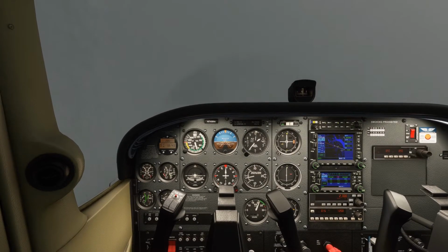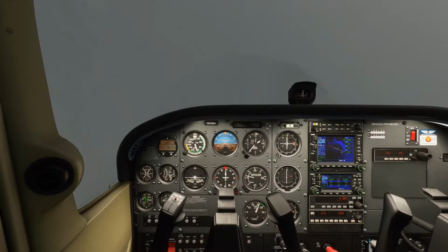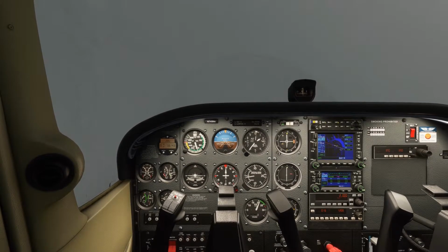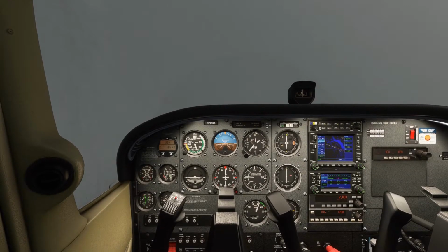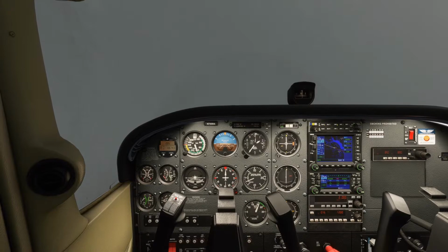After that time, 5 times the ground speed gives us the rate of descent required for a 3-degree glide path. So the ground speed, I'm going to be flying flaps 10, 80 knots. So with zero wind, that'll be about 400 feet per minute rate of descent. So we'll see how that works out for us initially. And there we go, so we can now establish that.